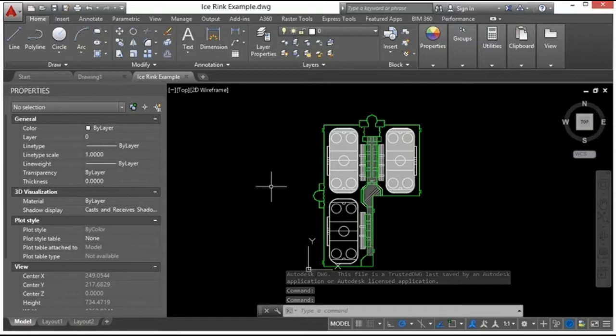It's a model space viewport. In paper space, that viewport gives you a view of what's in your model. Now, viewports in model space do that too, but it's not for drawing purposes. It's for modeling purposes. Model space is where your model goes, your information. And paper space is where your drawing information goes. That's your view, your title blocks, things like that. And then you have your viewport in that paper space to look at your model data.